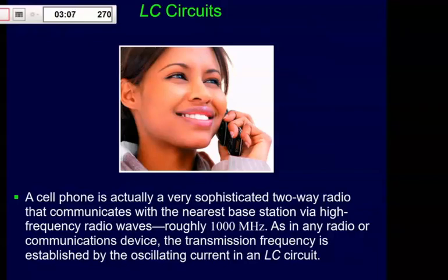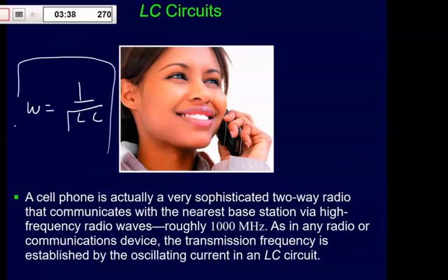And if you have an LC circuit, it's just like when we talked about resonance, back in 2A. These circuits, if you try to drive them with some frequency that's not close to their resonant frequency, which is the one we just found, you're not going to get much current. So these circuits really want to accept this special kind of frequency.